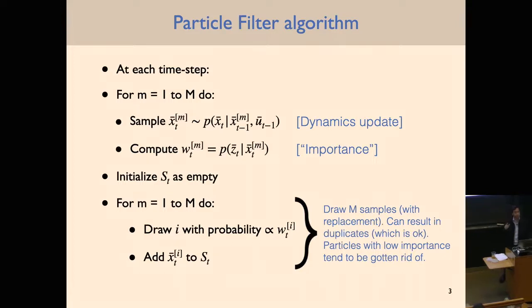All right, other questions on the algorithm? I'm happy to go over it again or clarify anything that's unclear. Throughout, and maybe especially at first, are you sampling uniformly from the state space? At the initial time step, before you see any measurements, you have some initial belief about where your robot could be. That was related to the question about how you choose that initial belief. If you have some knowledge about where the robot is likely to be, then you could have more particles there.